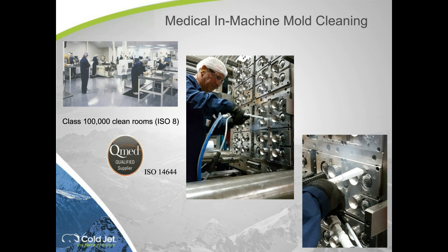Mold cleaning is often done just in an open environment with good filtration. Sometimes it's in a clean room. We've had success in what I call the ISO 8, the class 100,000. Somewhat depending on when you take the isokinetic probe into the room, what does the room read in a static state before we do a dynamic clean? If we walk out there and the room's reading 96,000, we're probably going to push it over.